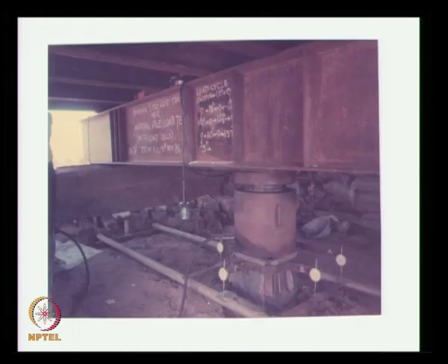This shows the photograph where you are seeing these 2 frames attached to some benchmark, then there is one plate which is connected to this test pile where you measure the deflection. This is the jack, the piston, then you have this grillage with an I section with a web stiffener so that the load is transferred.